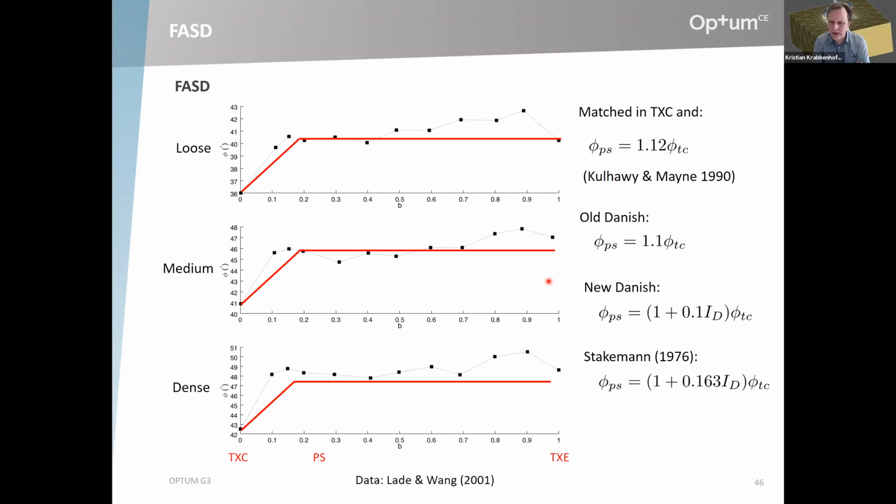So it's not exactly a routine thing to do, but the point I was making with these 4 equations here is that there is actually quite a bit of experience and knowledge out there, and some of these equations are in the codes. So in any given situation, what exact number should you pick? I think the old Danish one, the 10% one, is probably as good as any.